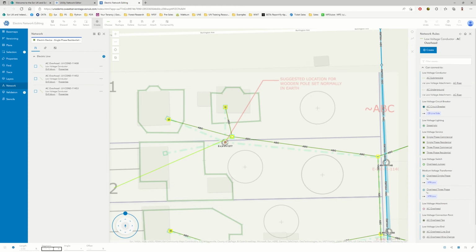In this case, we are going to do it on a 77 feet length line. You can see that the application is locking the length of the cable to be the one that was inputted by us in the COGO tools. So we are going to draw it till the distance allows us. And now after we have drawn, we are going to add a new connection point.